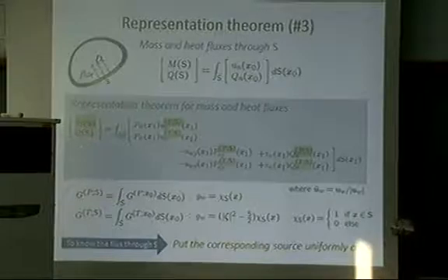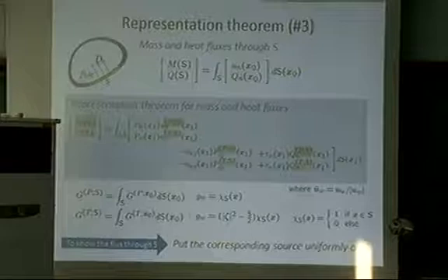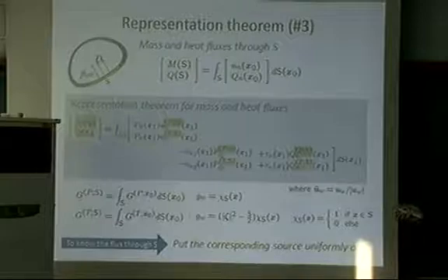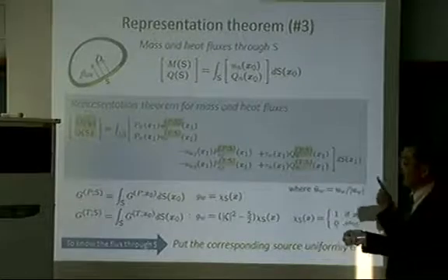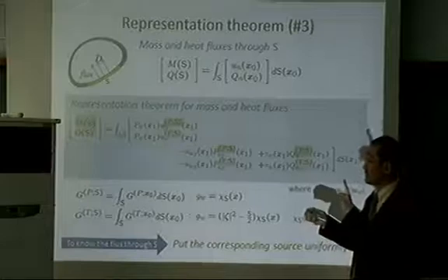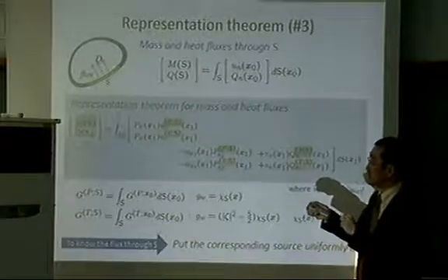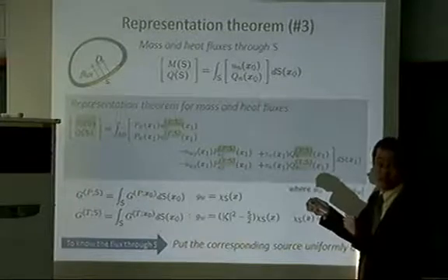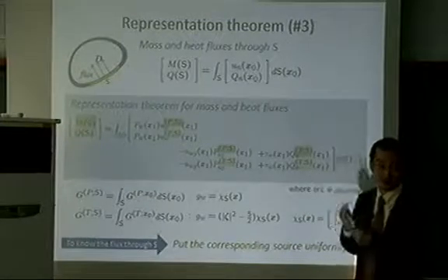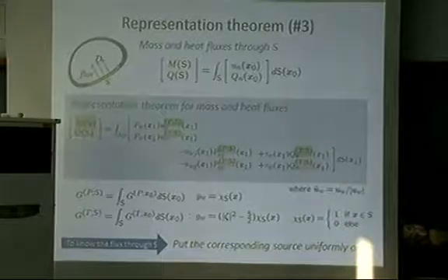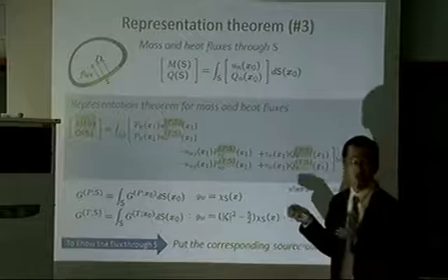This part is heat flux. If you are interested in the heat flux passing through this surface, you have to solve only one problem, such that you heat uniformly here and find a solution for this situation. Then you can obtain the heat flux for any situation.